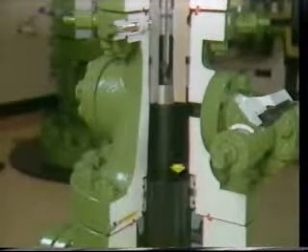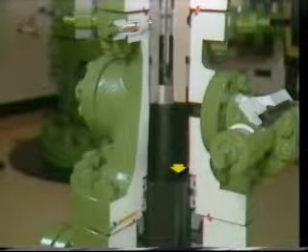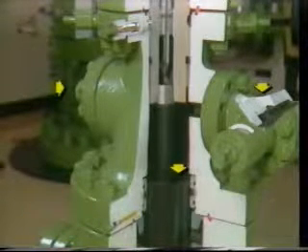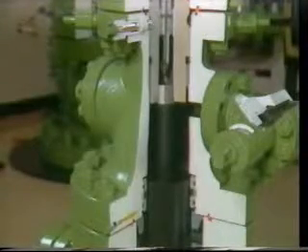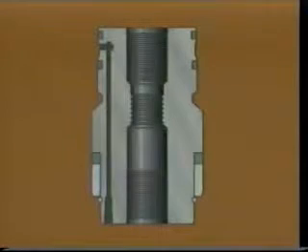The annulus between the tubing and production casing is accessed through one or both of the outlets on the tubing head. The tubing head and hanger are critical components on high-pressure flowing wells, since this seal is exposed to the subsurface pressure. A mandrel-type tubing hanger is the generally accepted design for supporting the tubing.